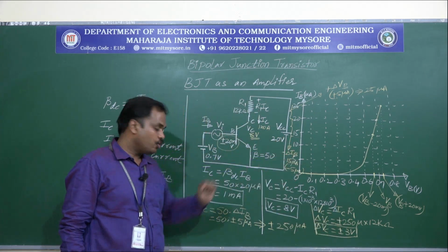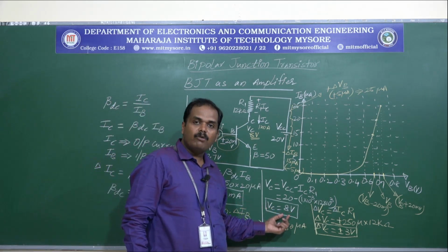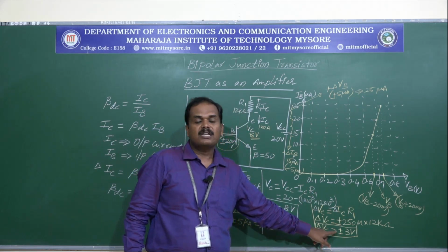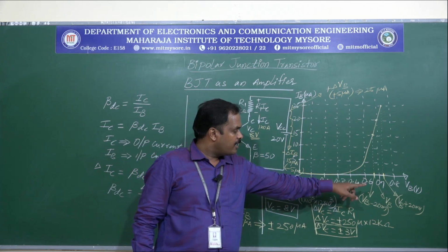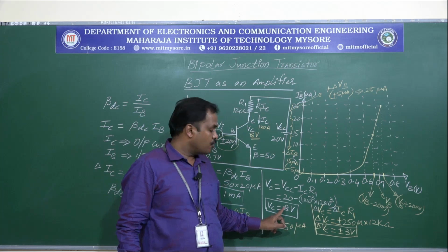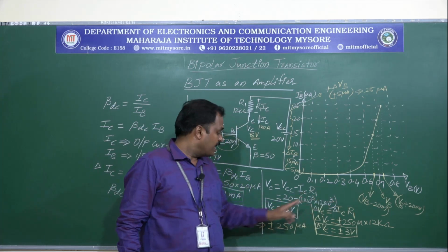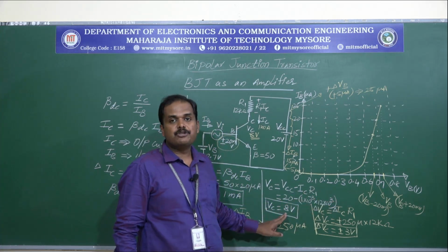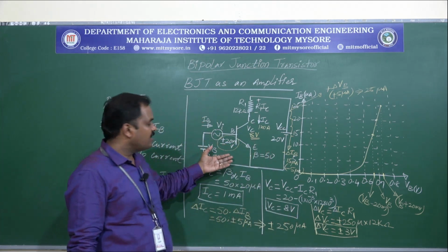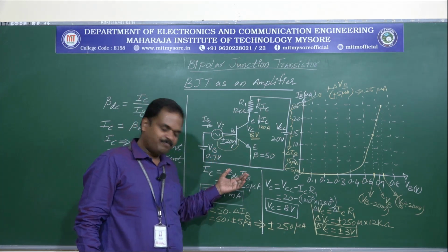Before considering the change in the input voltage, we had VC equal to 8 volts. Now if we change the input voltage, we have a change of plus or minus 3 volts. If we change the input voltage by plus 20 millivolts, the collector voltage will be 11 volts. If we change the input voltage by minus 20 millivolts, then the output voltage VC is going to be 5 volts. From this we can understand that the transistor can also be used for voltage amplification.